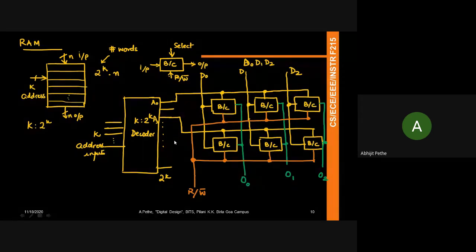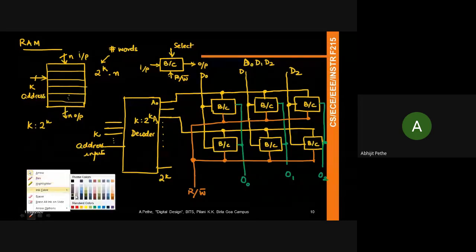Because sometimes there might be imperfections in the circuit associated with a particular bit cell, or you might have made a timing signal which is not sufficient for the entire write process to occur. So in those cases, it's always a good idea to check and ensure that what you wanted to write has been written into the bit cell.